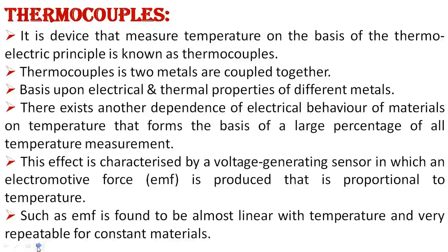A thermocouple is two metals coupled together, based on the electric and thermal properties of different metals. There exists another dependence of the electrical behavior of material on temperature that forms the basis of a large percentage of all temperature measurement. This effect is characterized by a voltage generating sensor in which an electromotive force (EMF) is produced that is proportional to temperature. Such EMF is found to be almost linear with temperature and very repeatable for constant materials.